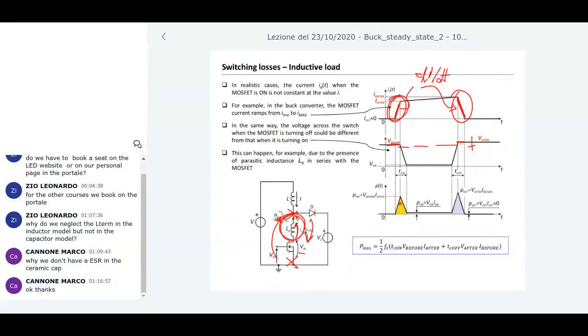We can have a slight modification of this triangular waveform. If you recompute the area I did before, with this slight modification in the values here, you get these general expressions. One half, this is a shape factor, always the same, triangular waveform.